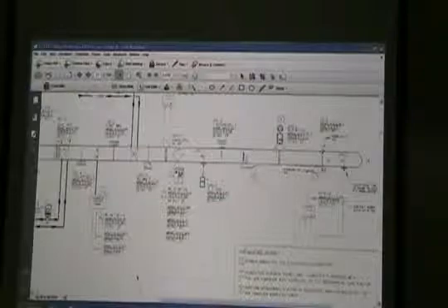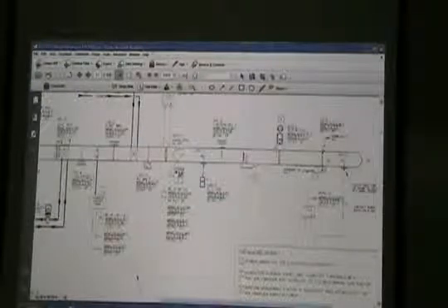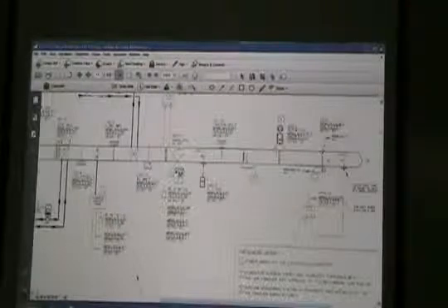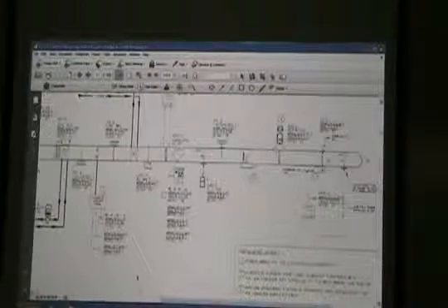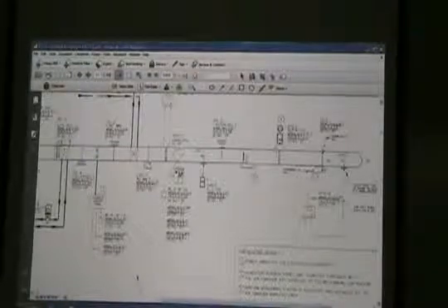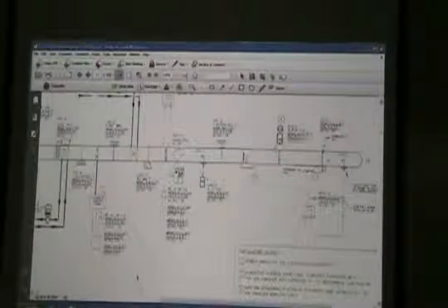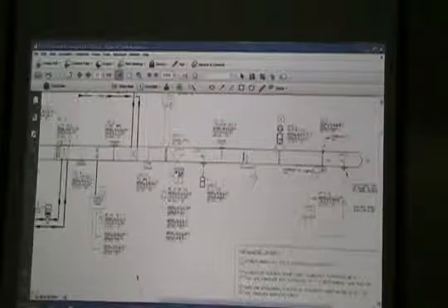Sometimes some engineers call for it to be a transmitter, and we just vary the signal to keep it below a certain level. Yeah, that could be just an on-off switch type of sensor. It's a transmitter, so it's actually telling us what the humidity is. So there's the high limit.